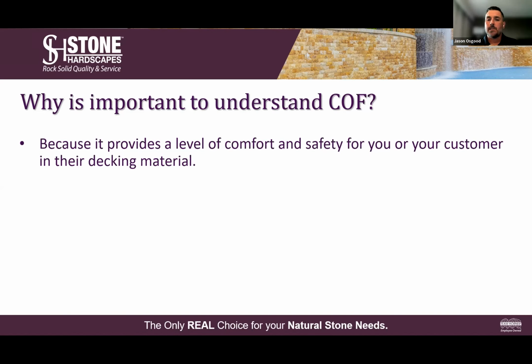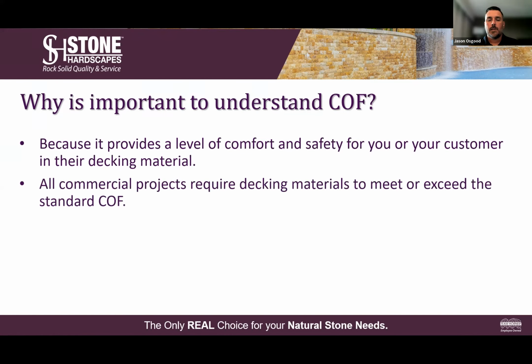But we can confidently say that everything that we have passes those testing. And because they pass that testing, there's a level of comfort and safety that you can provide for your customer, and that customer can provide for their family. The other most important aspect is you cannot put a decking material down on a commercial project that does not meet or exceed the standard coefficient of friction. That is why it's incredibly important to understand what the COF is of the deck material that you purchase, or the deck material that you provide.